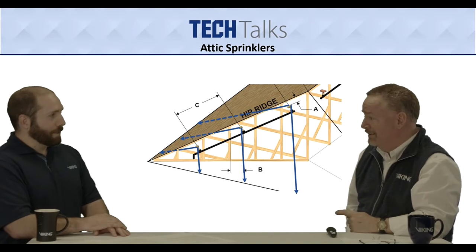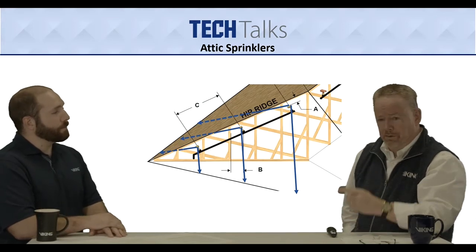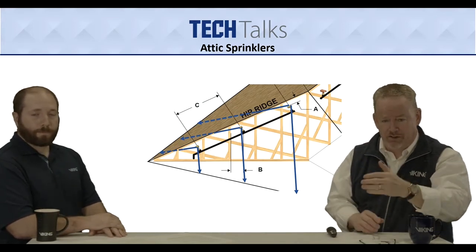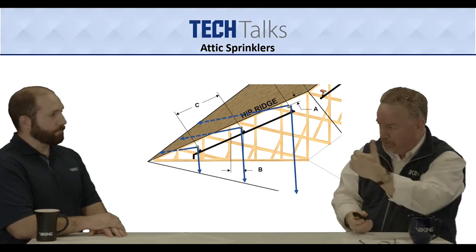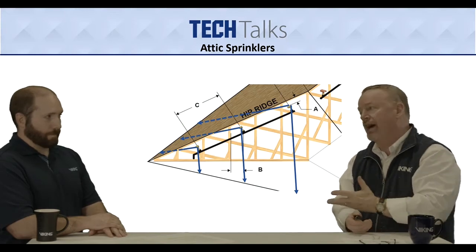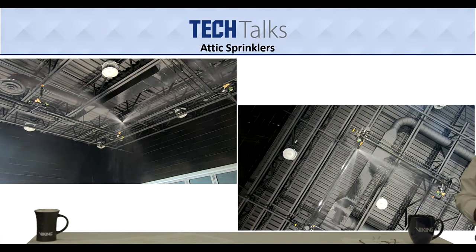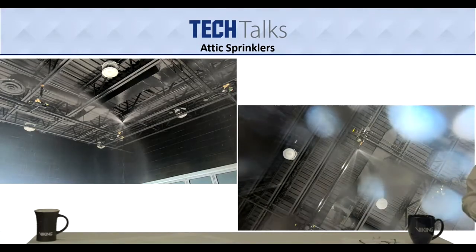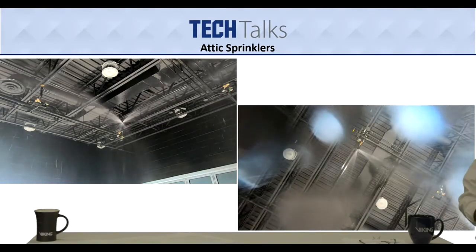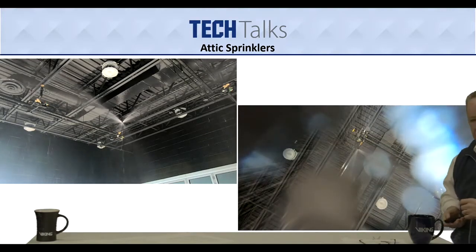6-foot spacing again. How about that? Yep, and these sprinklers at each angle will throw up to about 28 feet. So the nesting you were talking about is right, as you go down that slope, each of those spray patterns is nesting right into the other one's spray pattern. So you don't have a dry area there either. Correct. To show you that, we'll demonstrate this one a little further. You'll see that 90-degree thing, a little less than 90 degrees, obviously, but you can see the capability of that particular sprinkler. Now envision nesting another one down in front of it and another one in front of that as you go down the slope.